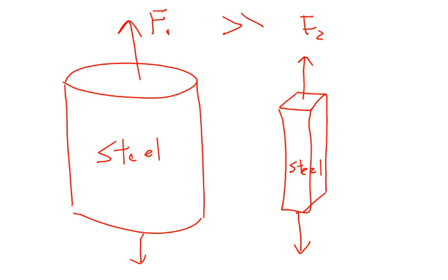force 2 here. Why? Because stress, if you remember, is this force divided by the cross-section, and since the large column has a much larger cross-section, in order for me to have the same stress as the smaller column, I have to apply much larger forces. So I have the same stresses, okay? Am I going to get the same deformations?